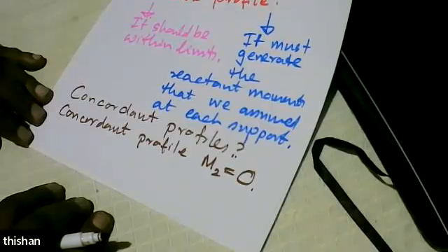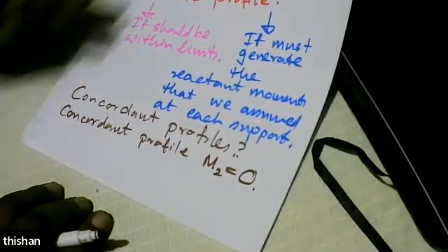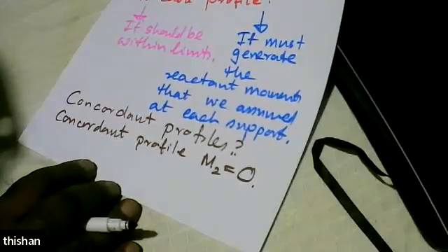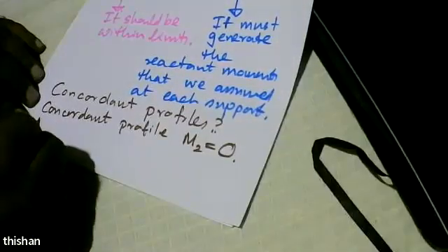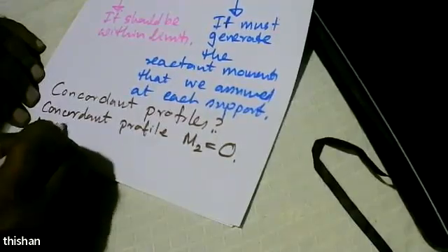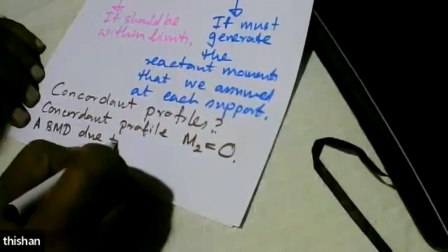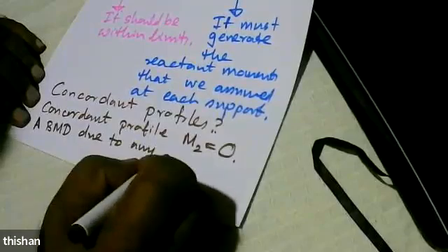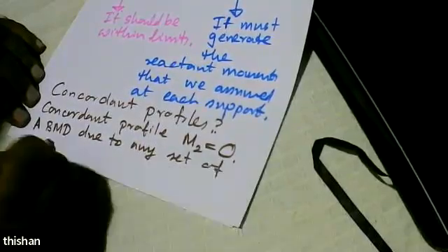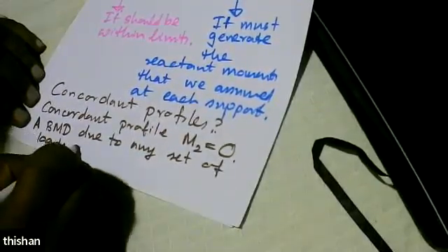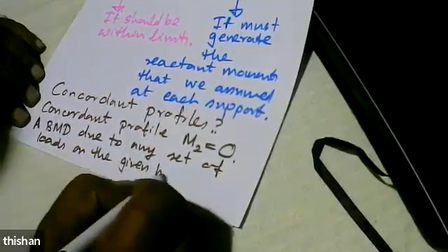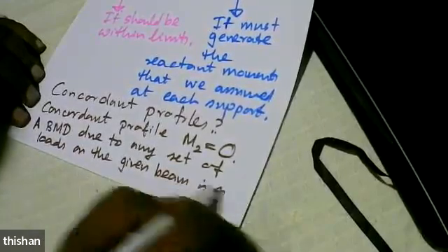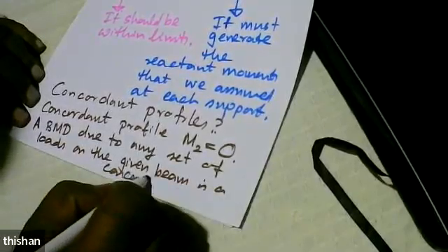And again, some theory comes to our rescue. And the theory is simple. A bending moment diagram due to any set of loads on the given beam is a concordant profile.